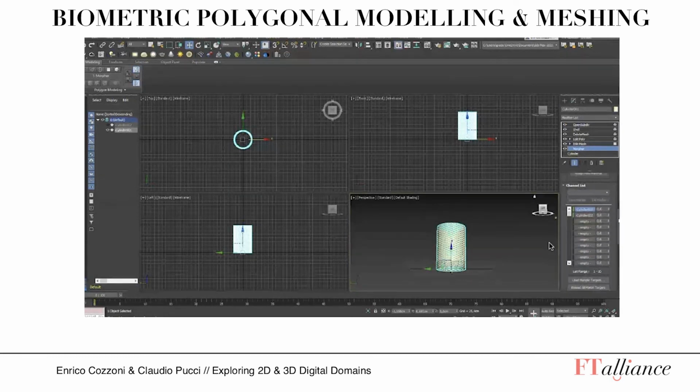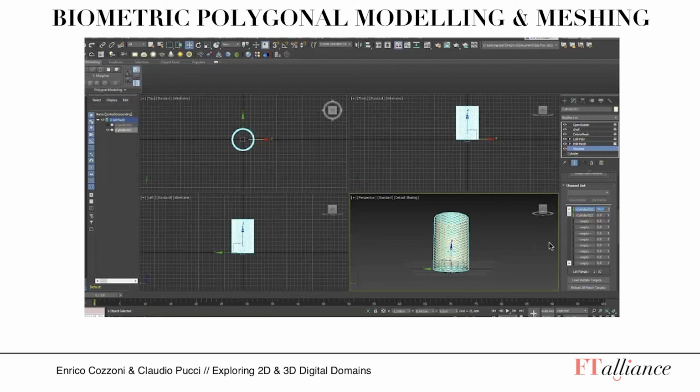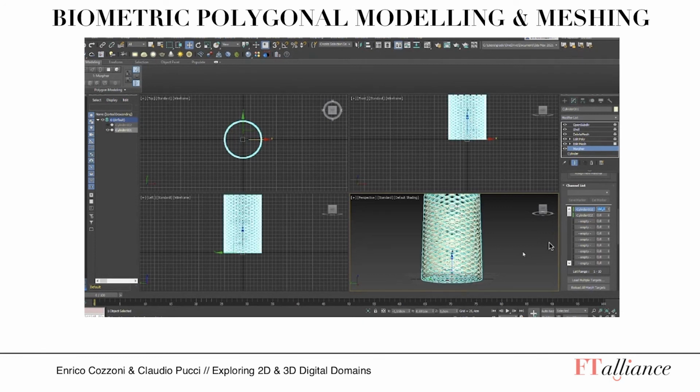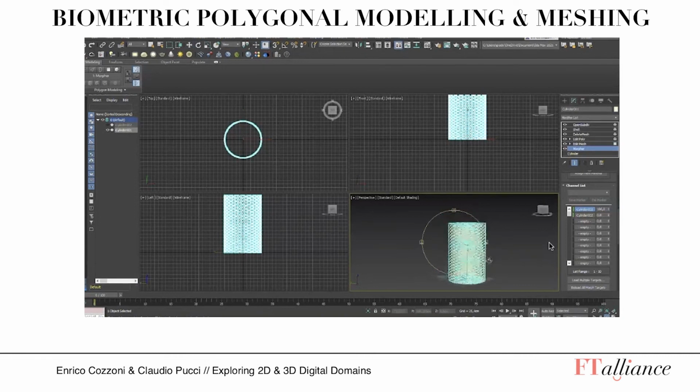It means that if you want, starting from a basic primitive geometry, to modify that geometry through morphing, as I told you, you need to create a copy of the original geometry that, and this is an important aspect, needs to have the same number of points as the original shape, and you can simply play on the copy of the geometry that you have generated, modifying the geometric characteristics. This is a cylinder, so it is not a complicated geometry.